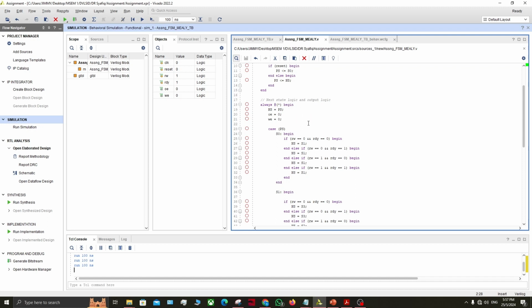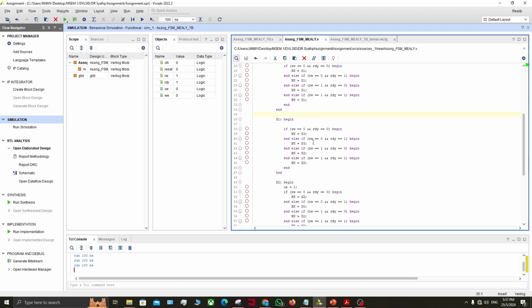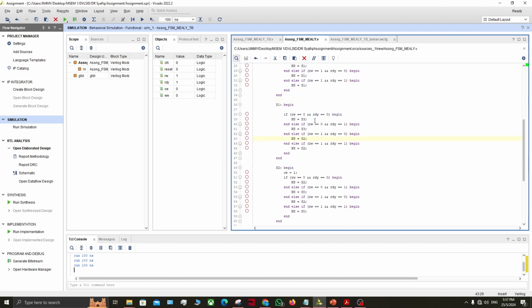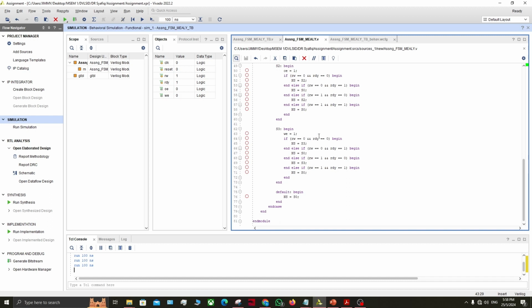Okay, initially the NS and PS outputs are 0. Let's look at S0 here. Like the truth table or the state diagram, all inputs during S0 will lead to the next state of S1. But for S1 there's a new direction. For 00 and 01, it will go to S3, and 10 and 11 go to S2, just as in the state diagram. And for S2, 00 and 10 will lead to next state S2, and 01 and 11 will go to S0.